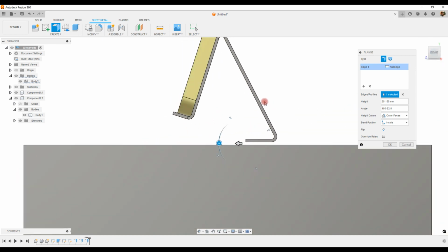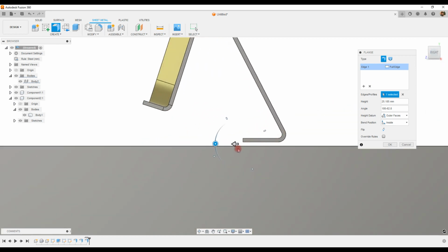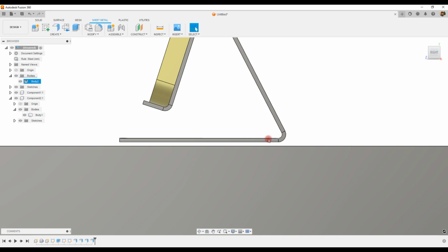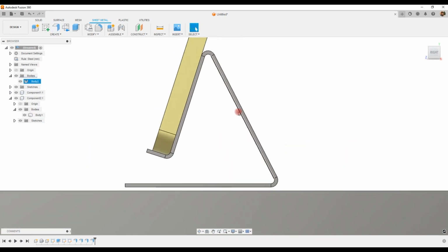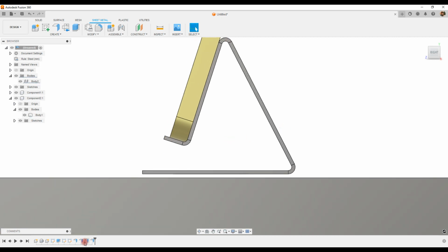And let's take this side view so we'll get to know. So there is a gap over here, and let's give it a height of 90 mm. Now there is a gap over here, which basically means that the leg lengths which we have entered are incorrect. We can always modify it to match the surface.